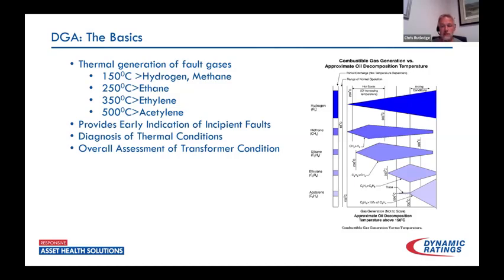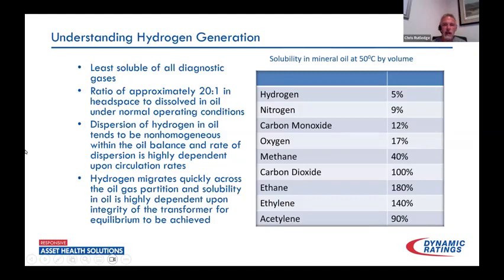And this is something that served me very well throughout my career, is understanding, if I see a bunch of ethane, I've got a pretty good idea of what that hotspot temperature is, and as it relates to what I would want to see around 110 degrees C of that hotspot temperature. So I'm that much hotter. So this is a good guide for kind of understanding that.